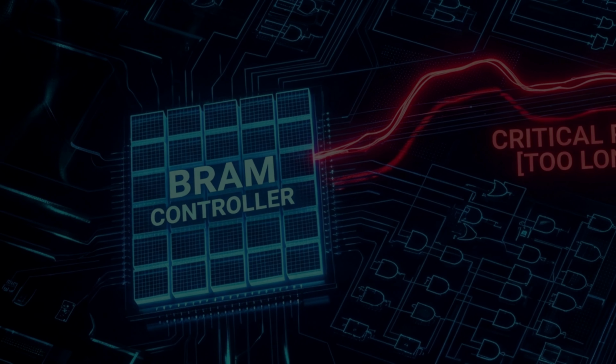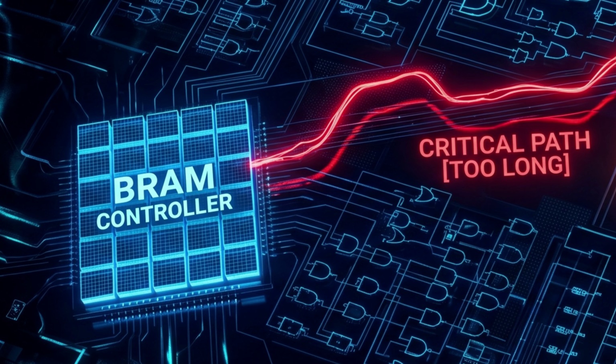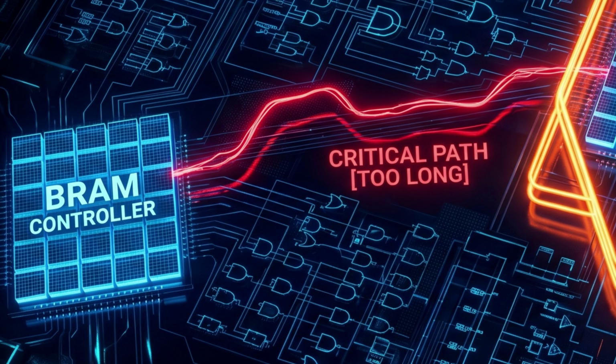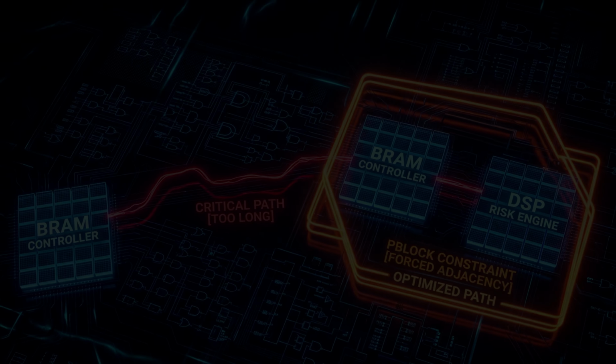We examined the critical path in Vivado. The source of the longest delay, the data path between the BRAM controller and the DSP RISC engine. These two blocks have not been placed close enough to each other. Solution: a Pblock constraint. We tell Vivado to confine these two modules to a specific region of silicon. Physical proximity is enforced. The wire shortens and the delay drops.